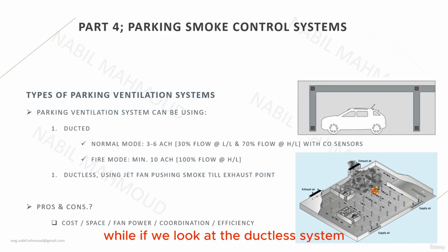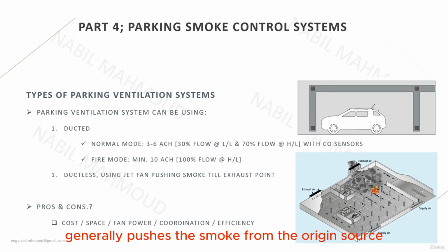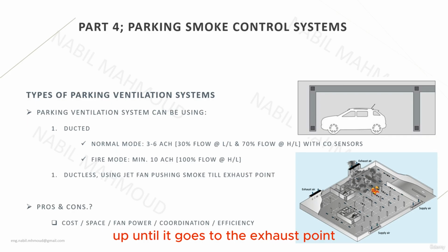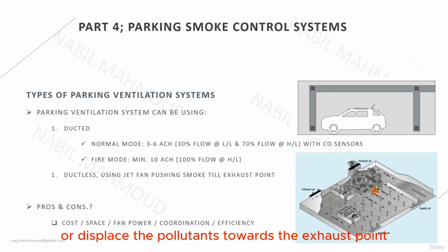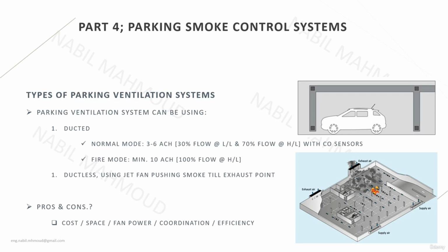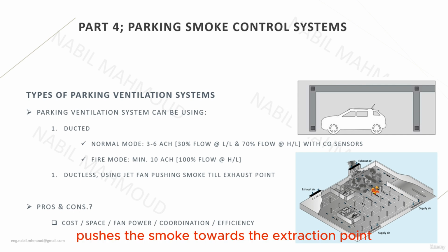While if we look at the ductless system, we will see that it generally pushes the smoke from the origin source, or from the origin point, up until it goes to the exhaust point. And in some cases it pushes the supply air to displace the smoke, or displace the pollutants, towards the exhaust point. So it doesn't necessarily suck the smoke, but it rather pushes the smoke towards the extraction point. And this is the main difference in the concept.